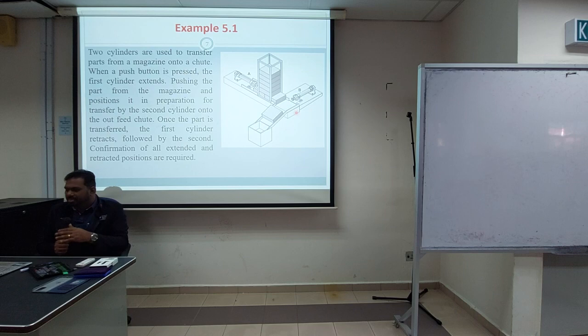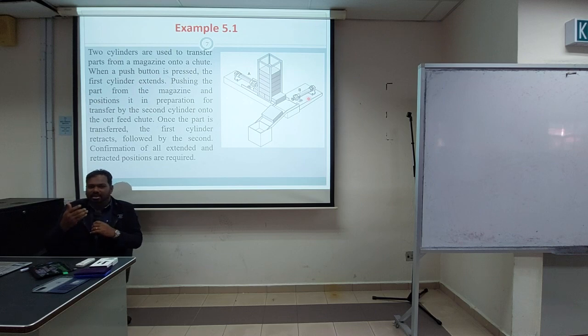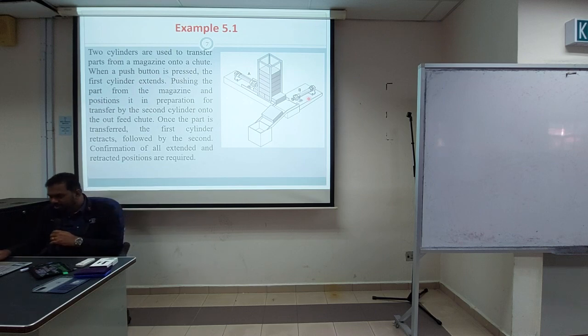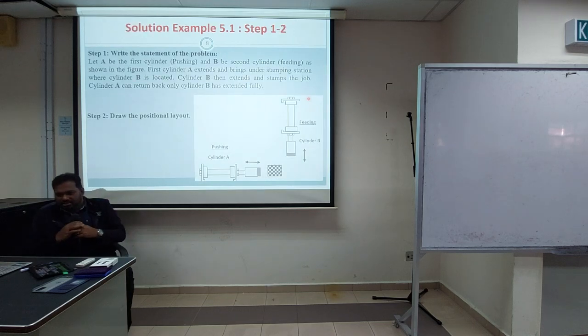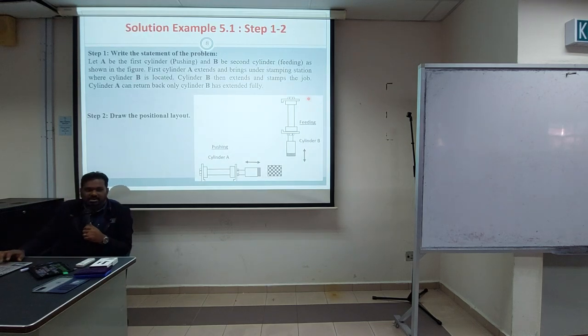It loads. So what will happen if A plus, then B plus? Cylinder A is still occupying the position, so cylinder B cannot push. So A has to release first. That's why it's A plus, A minus, B plus, B minus. So it's a simple loading solution. Okay, so how do you want to design using the classical way?